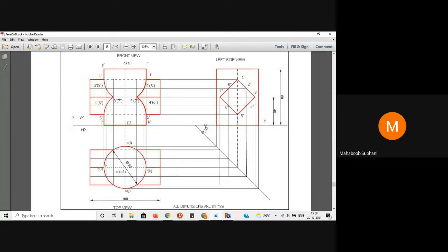So the invisible lines we will be using are the hidden lines. Whatever part is inside this solid is not going to be visible for us, so we are not highlighting that part. That's why it is shown in hidden lines. So you might now know the purpose of the hidden lines, and we only highlight the part visible for us.